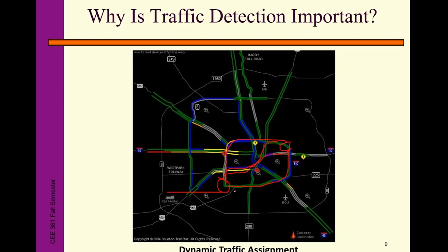So you can have, for example, a dynamic message sign that shows the congestion level and travel time for each route, and then let the travelers decide which route they want to take, and what's the fastest way they can choose, and eventually optimize the traffic assignment network-wide. So we reduce the travel time for everyone, and eventually reach the equilibrium status.